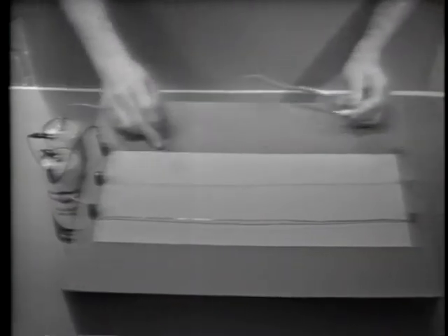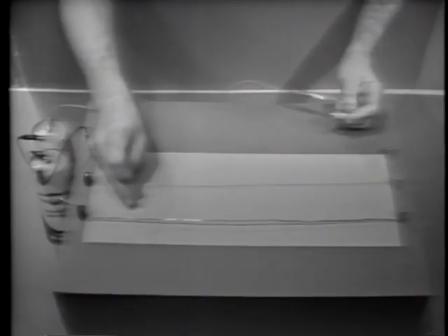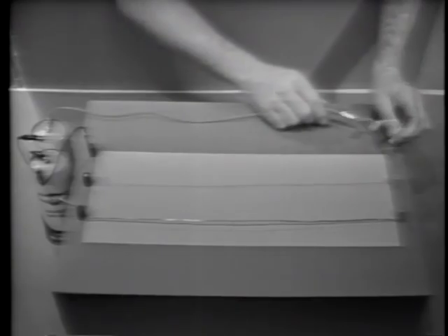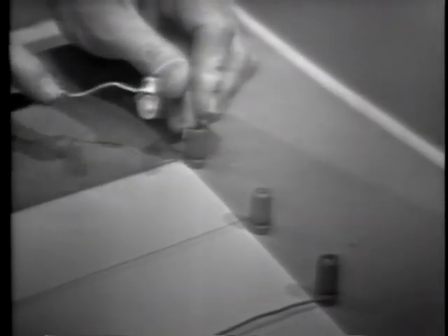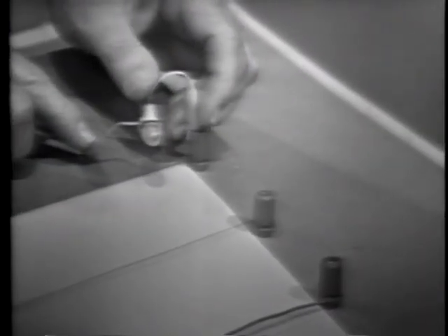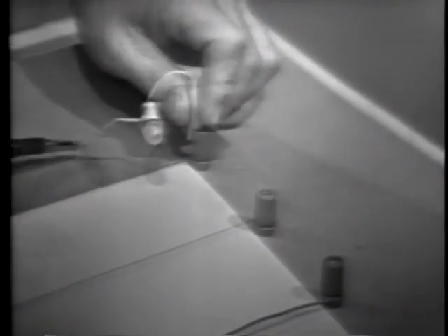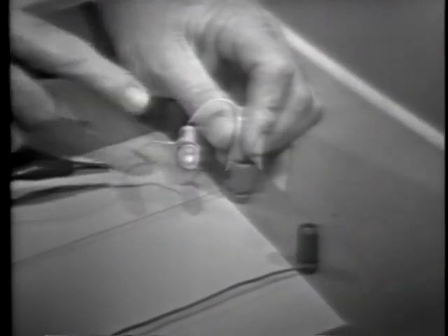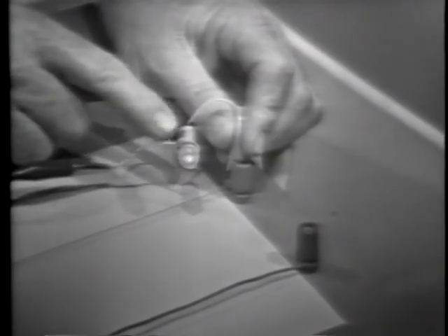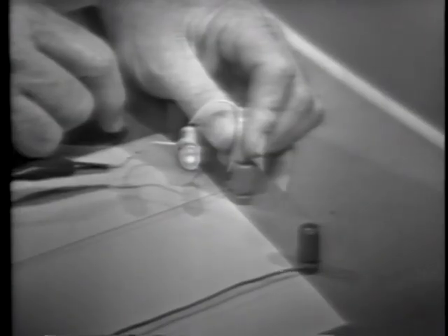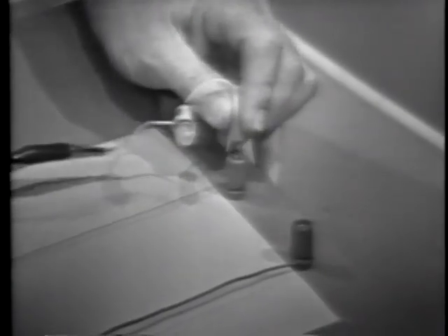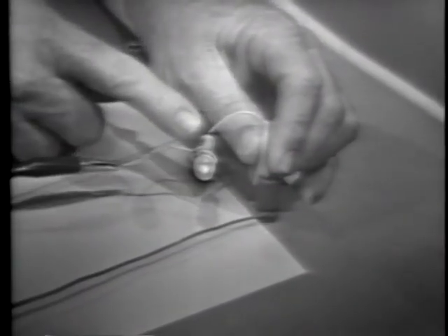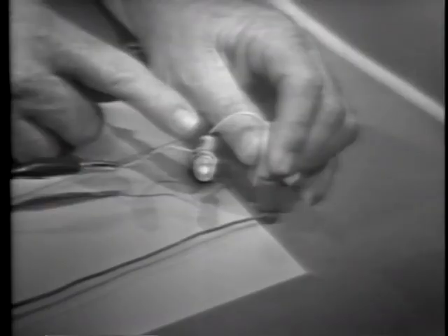Now in the next one, we're going to increase the diameter of the wire. Let's see what happens to resistance as we do this. Of course, with the small diameter wire, there's very little current through the bulb. Let's go to the next one. As I increase diameter, there's more current through the bulb. This means that resistance decreased. Let's go to the next one. Increased diameter, more current through the bulb. So resistance must have decreased.